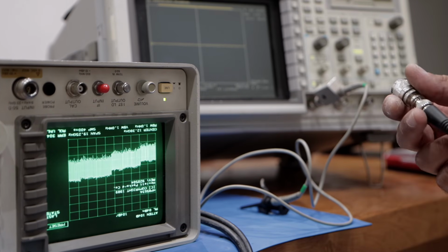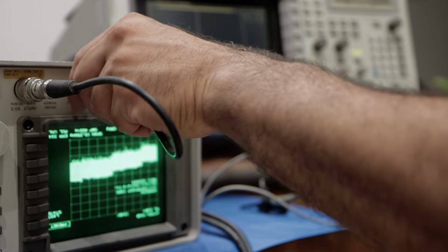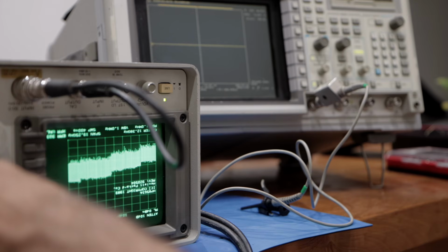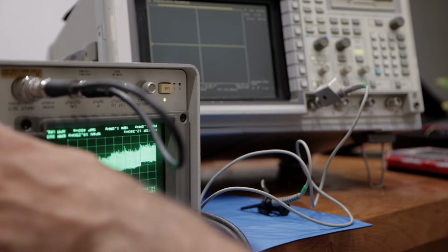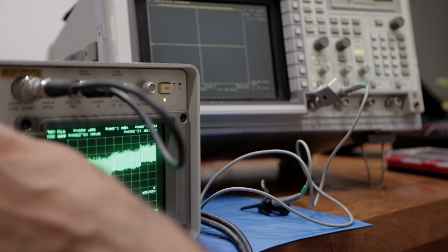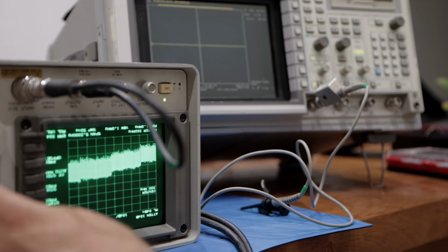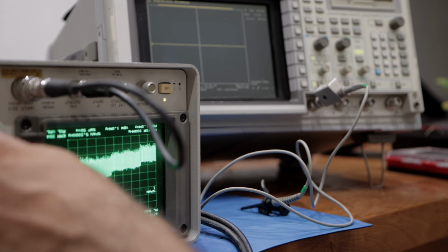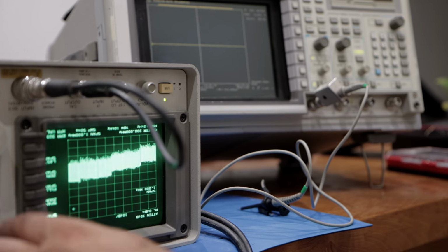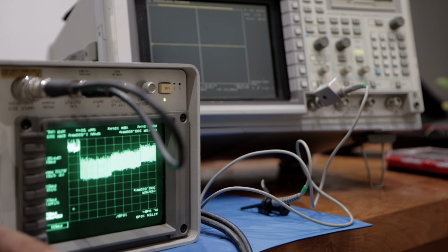Let's take a quick look back at this wild journey so far. First off, I finally managed to get this stubborn attenuator clicking. But we are not out of the woods yet, because those resistor pads still need a closer look. Then, I swapped out the faulty A21 oscillator, which finally gave me a rock-solid 10 MHz reference, and that alone got the analyzer booting up on its own, just like it should. So for me, it's still a win. For the first time in forever, this HP8563A is actually doing what it was built for, analyzing signals.